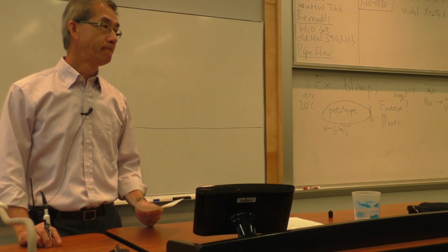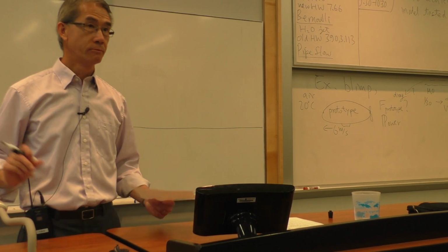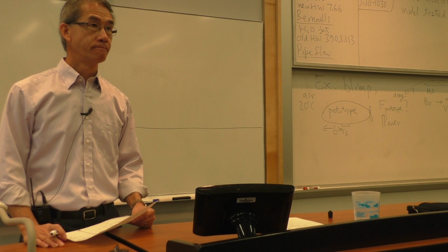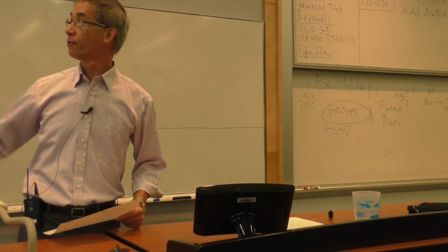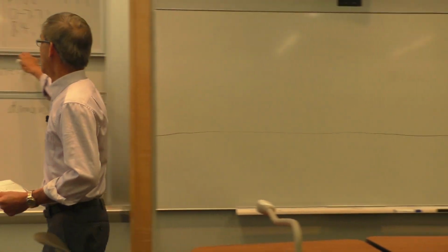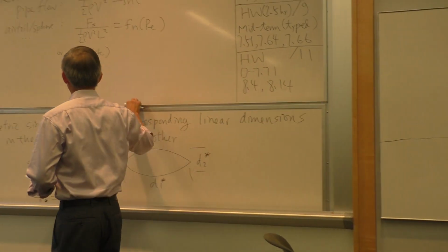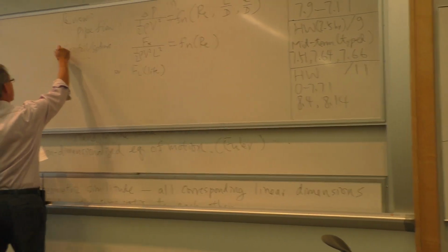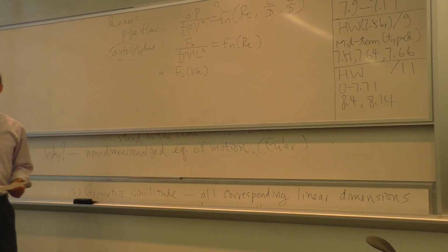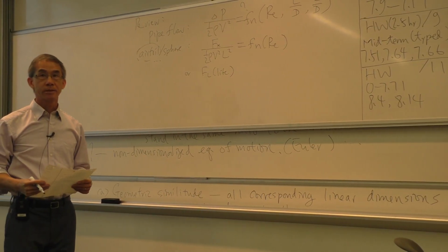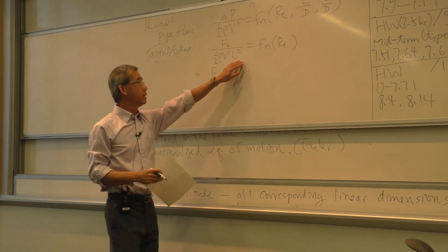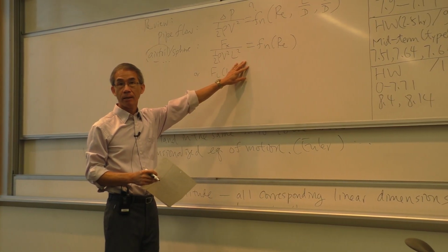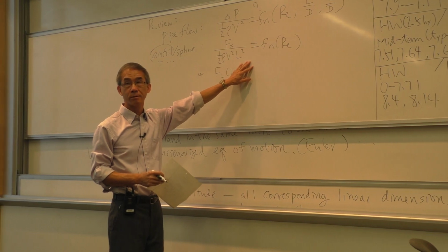Say it again? The airfoil. The airfoil. Different shape, but same physics. And I'm after the drag force, which we did last time for an airfoil shape, but whether it's an airfoil, ellipsoid, or sphere, it's the same dimensional analysis, which we have done. And the answer is, I only have two pi terms.